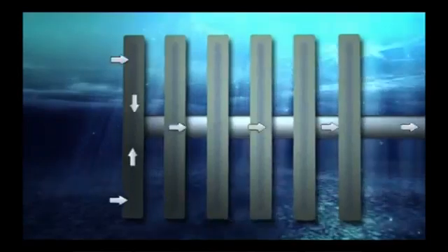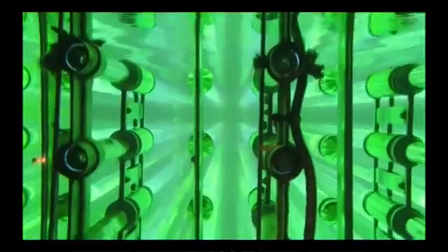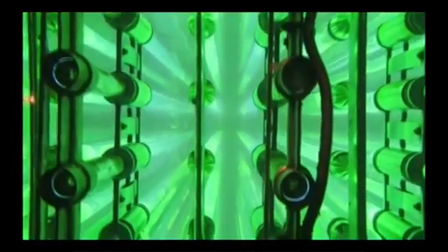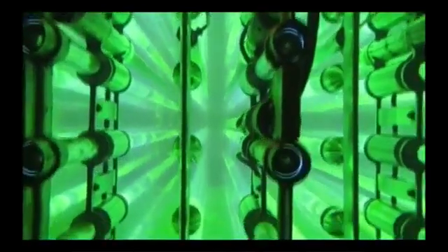This sedimentation basin is referred to as the secondary clarifier or final clarifier to differentiate it from the sedimentation basin used for the primary settling. An important element in trickling filter design is the provision for return of a portion of the effluent, that is recirculation, to flow through the filter.